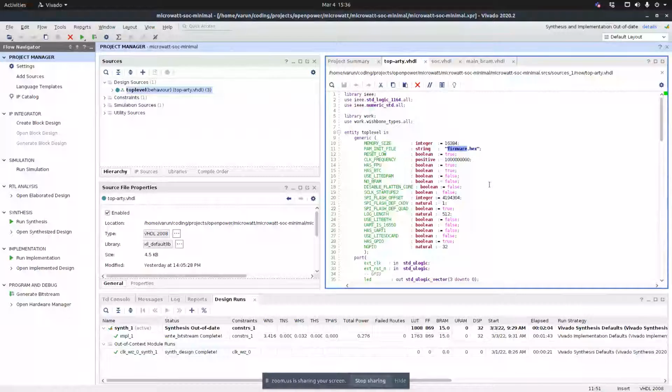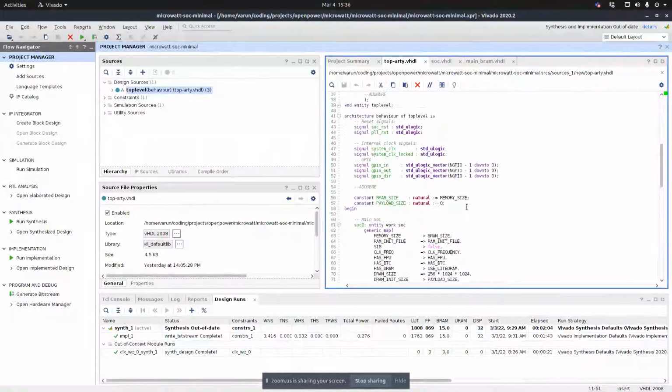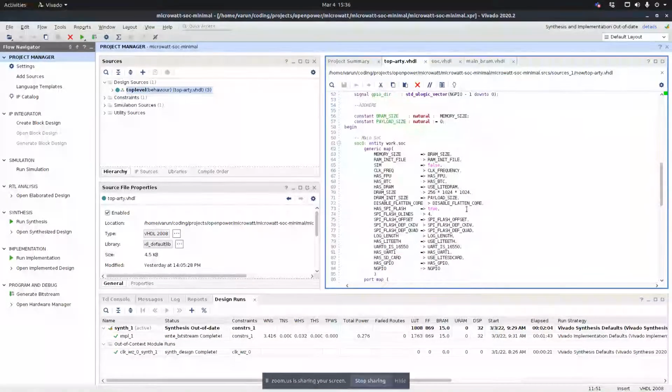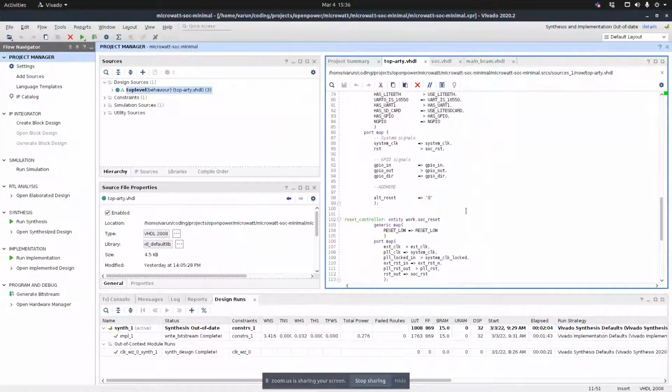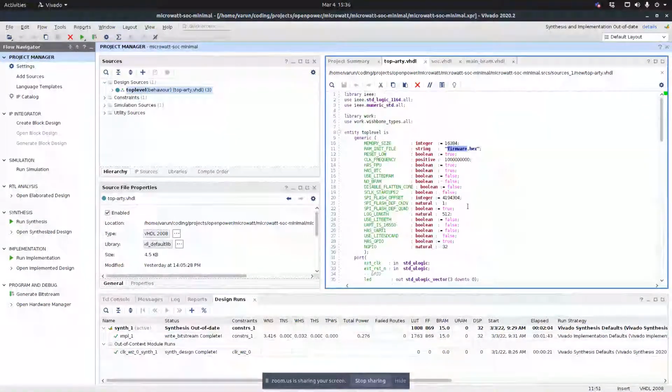memory. So what we are currently doing is, using Verilog and VHDL, we can initialize our RAM structures using a hex file. So during synthesis, it will read the content from this hex file, and it will be used to initialize your VRAM contents, and it is part of the bitstream. So basically, your ELF becomes part of your bitstream, and you can simply load the bitstream to the FPGA, and the VRAM will have that ELF automatically, and the core can start executing the ELF.